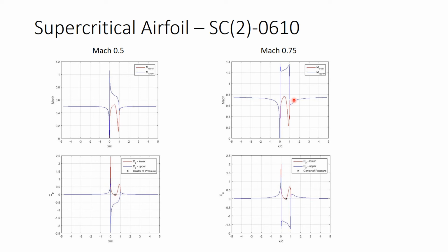And really, this is an ideal scenario for a transonic airfoil or a transonic wing, because we want the center of pressure to not move around a lot, and having a small shock at the leading edge versus having a small shock at the trailing edge of the airfoil is going to produce very similar results in terms of the location of the center of pressure, because we don't have this large discontinuity in the lift characteristics of the wing or airfoil moving around on the surface, which is what essentially causes the large changes in the pitching moment applied on the aircraft.